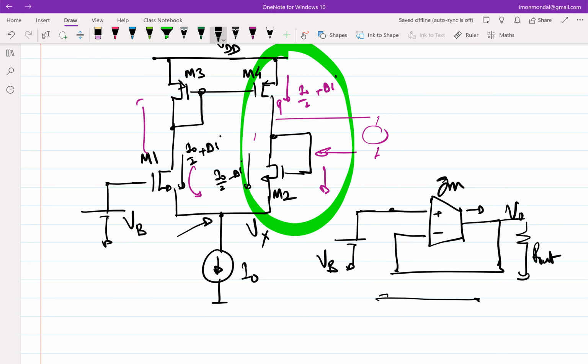Okay, fine. Anything else? So the source of M2 is, if at all, 1 by Gm, then we are inherently assuming that the gain of M2 is incrementally low. Right? Okay, we are assuming that the load at the drain of M2 is not high. If at all a current source is there at the top of M2, then definitely we will. Yeah, true. But the circuit is present, so how can we assume that this load is incremental?